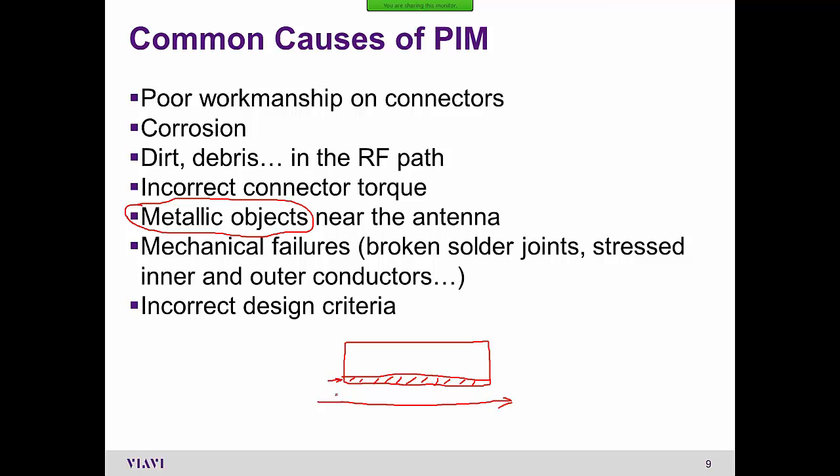If I've got a positive on the line here, I'm going to end up with negatives over here, or I'm going to end up with electrons moving back and forth through both of these. And if the shielding is too thin, you end up with electrons getting into the, say it's aluminum, and then you have electrons inside the silver, for example. And so that bimetal traverse of the electrons causes those electrons to move at different speeds through that material and create artifacts. So, now it's much better. A lot of the manufacturers are making sure their components are designed properly and don't produce PIM.